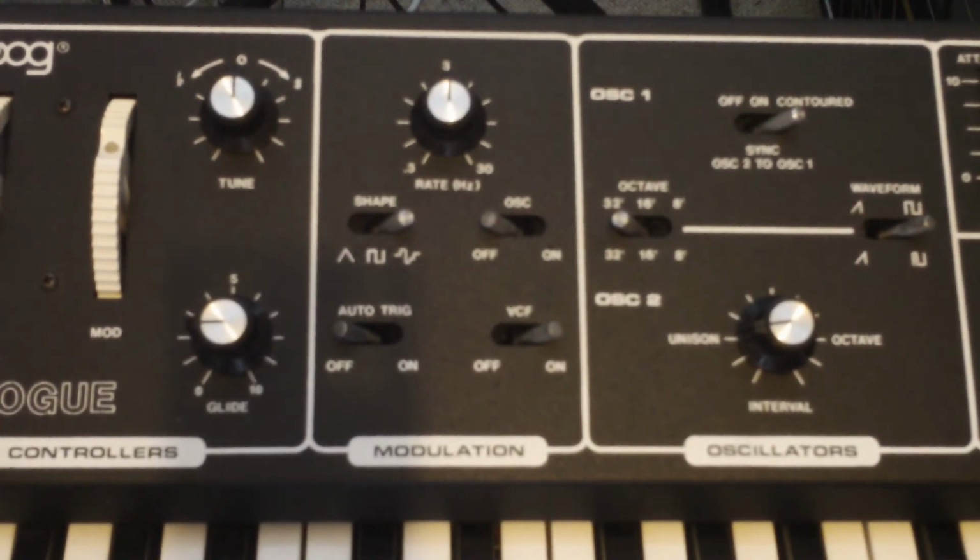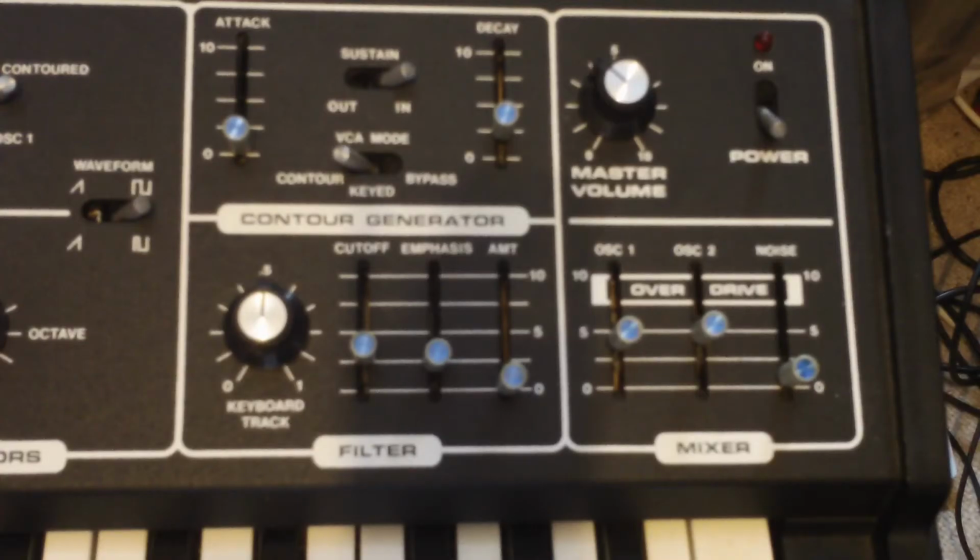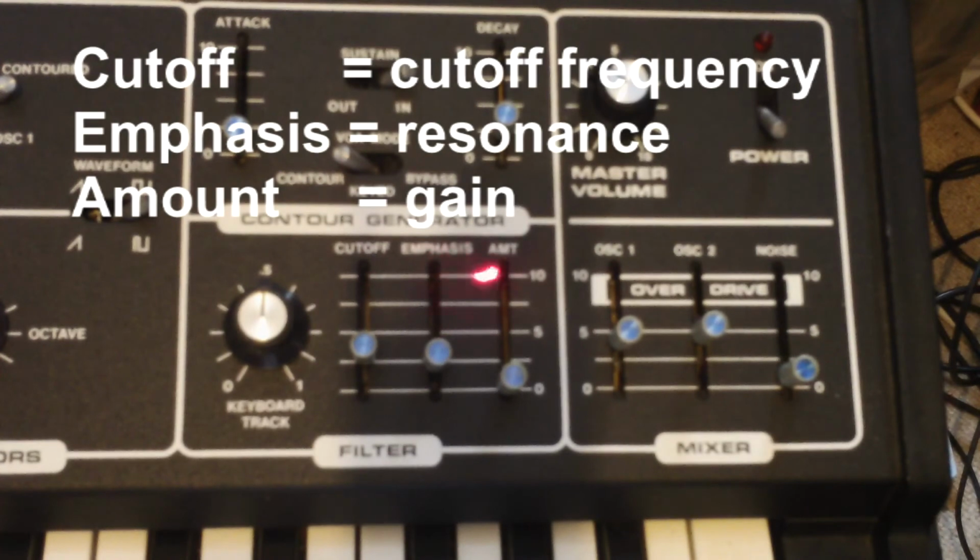Like the Odyssey, the Rogue has an LFO. This is the modulation section. I can set the LFO's frequency between 0.3 Hz and 30 Hz, and I can apply it to either the oscillator to get vibrato or the voltage control filter. The remaining controls on the Rogue are pretty basic. Here's my voltage control filter. I've got 3 sliders for cutoff, emphasis and amount, and that's it.